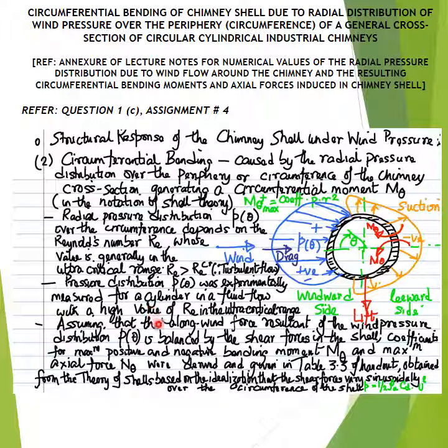can be determined by implementing the coefficients that are provided in table 3.3 of the annexure presented at the end of the lecture notes corresponding to the present lecture series, which have been obtained from the theory of shells based on the idealization that the shear forces vary sinusoidally over the circumference of the shell. Hence,